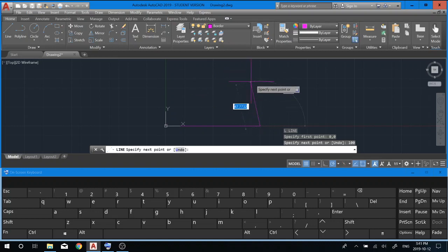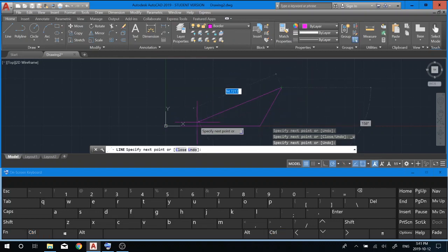Now I need to go lock it in vertical. I'm going to give it a direction, give it a value. Remember not to click your mouse key. All right. If you're up here and you click, right? Oh no, what do I do? Okay, don't worry. Just hold Control and Z, or you can go down here and click undo. So Control Z will undo, or you can actually physically go down to the menu bar and click undo, and it will undo that last point that you accidentally made.